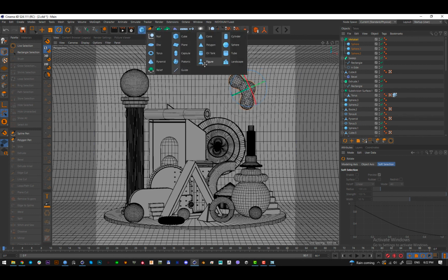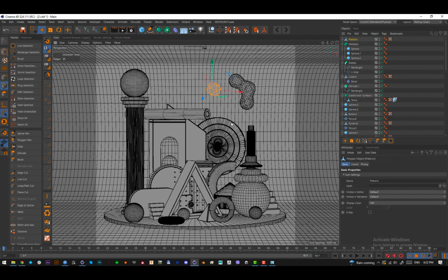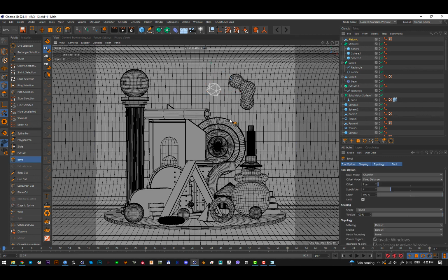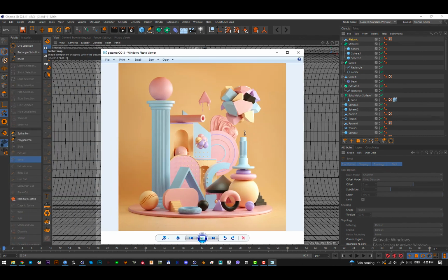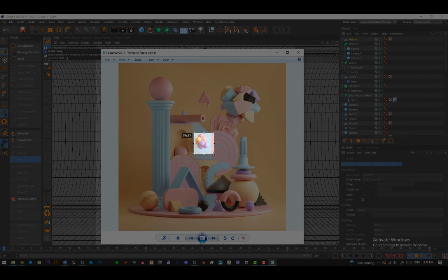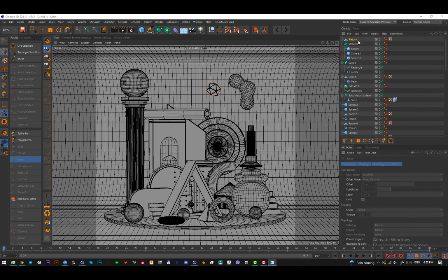Then let's add some sort of a platonic element, maybe here, like this. Okay, let's make it editable. Go into the edge mode, Control A to select everything, and M S to fillet it like this. Okay. And now let's see what else we want to add. We want to add some weird shape here, and we want to add this. So let's add a weird volume builder.